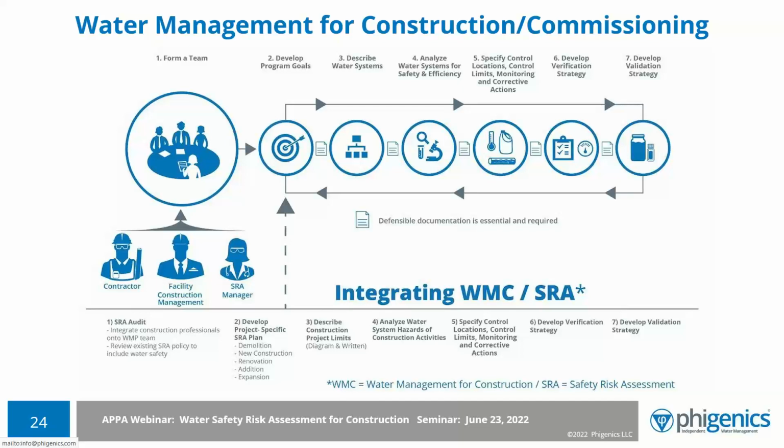And there's a couple of guidelines coming out on commissioning and recommissioning, and that varies by state, I should say. So you may be in a state where something is going to become mandatory to test. For instance, in New York, cooling towers have to be tested. So what the ASHRAE standard is about isn't the testing, it's about the process, and then you have to fill that in by determining that. So the good news is your team's in control of that.